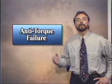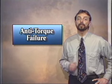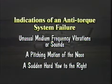The failure of the anti-torque system will result in a loss of heading control and is a serious matter which must be handled as an emergency. Some indications of anti-torque system failure include unusual medium frequency vibrations or sounds, a pitching motion of the nose, or, while at low speeds, a sudden hard yaw to the right. Some helicopters have a chip warning light that alerts the pilot of an imminent failure.